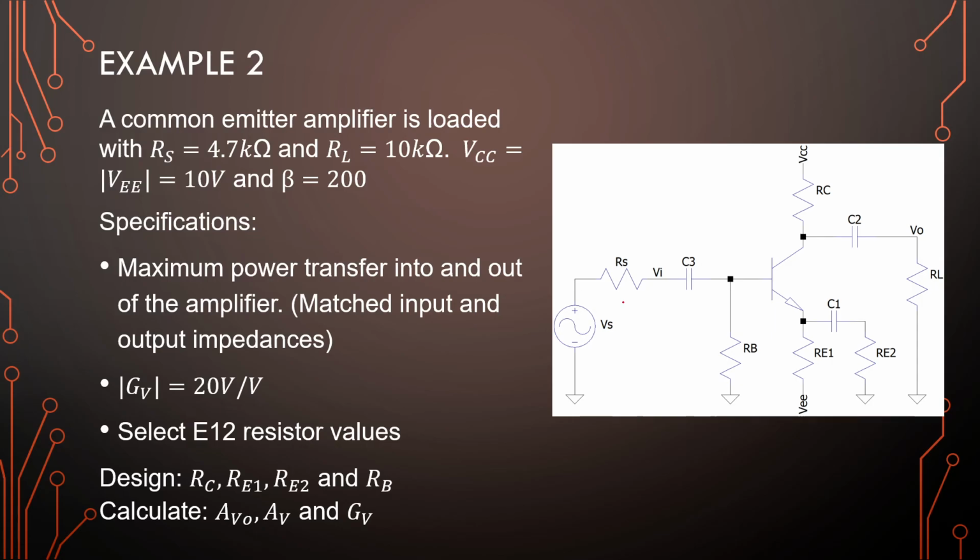For our next example, I picked a dual rail application here, and it is a split emitter. Always remember that this can also be a series combination, it doesn't have to be parallel. Then there's some different implications of how you run the equations, but that was discussed in analysis and in biasing structures.